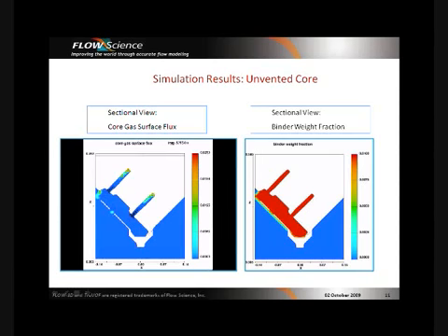And loss of gas into the metal is visible at the top and bottom portions of the top half of the jacket core. And the gas flow occurs at sites which have the lowest metal static head. Additionally, you can see desirable gas venting occurring at the prints into the mold flask. Let me show you these regions in detail now. You can see these lighter regions, which indicate regions where gas is blowing into the metal. And here we have venting occurring into the mold from the core.